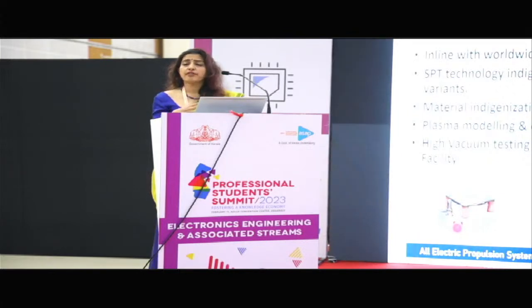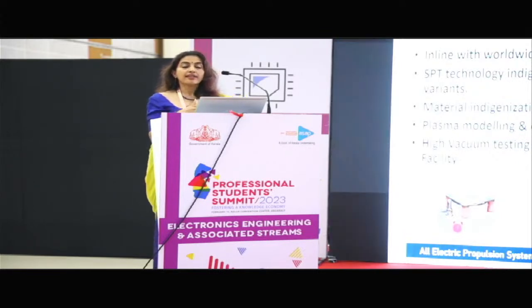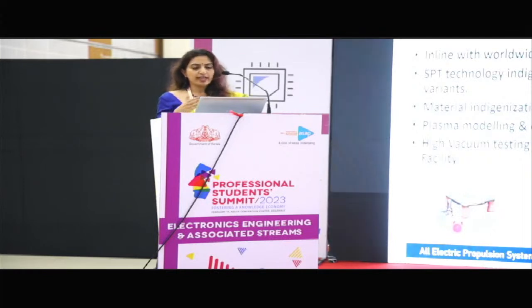So we have been working on this for a few years, and our team is supposed to supply various variants of this EPS for the ISRO satellites, and we are in line with the worldwide trend. We have different thrusters. The problem is that you know how thrust is built in a rocket or a satellite. When combustion happens, the momentum transfer happens to the satellite or the launch vehicle body, but here whatever is emitted is only electrons and ions. So we get only millinewton thrust, but over time we can expand, and we can achieve the same result as chemical propulsion. That is the whole goal. So what we have done is we have indigenized this SPT technology for an 18 millinewton thruster, a 75 millinewton thruster, and a 300 millinewton thruster. And the quest is going on, and we are still working on Newton engines and all that.